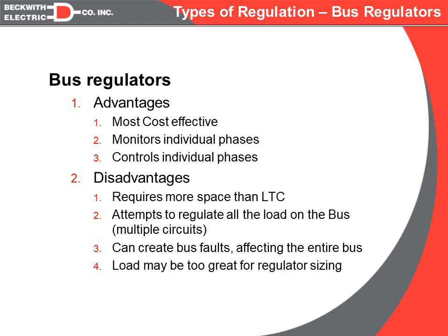Now, the next approach we can use is to go with bus regulators. Bus regulators are the most cost effective if you can use them. What a bus regulator does is it sits outside the transformer, so it's not physically attached to the transformer, but it is regulating the bus just like an LTC.